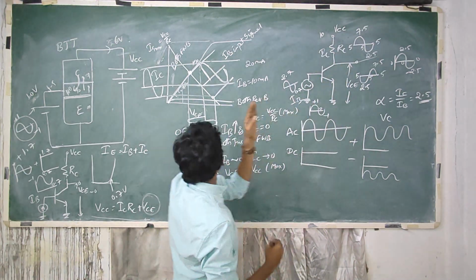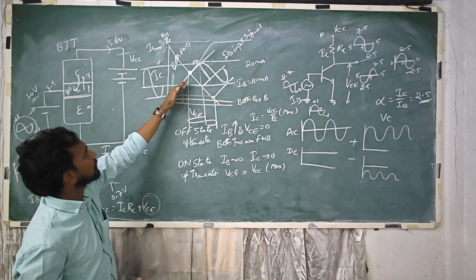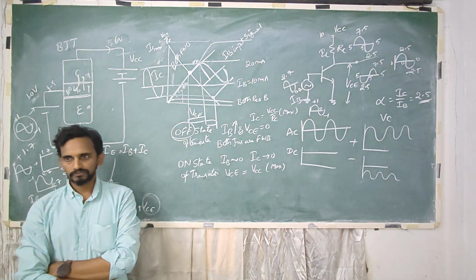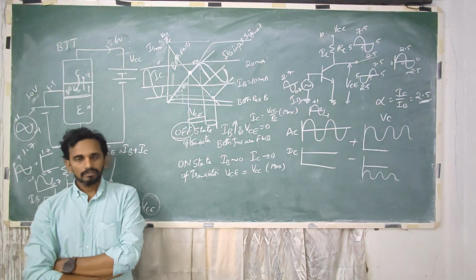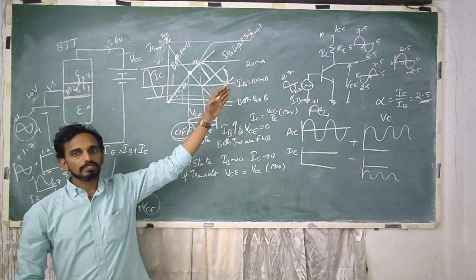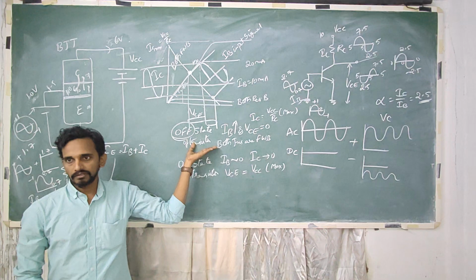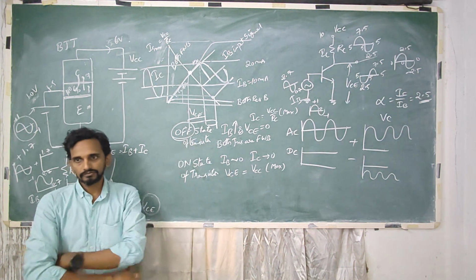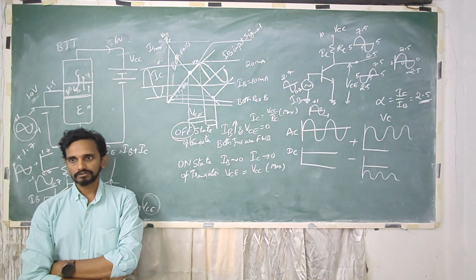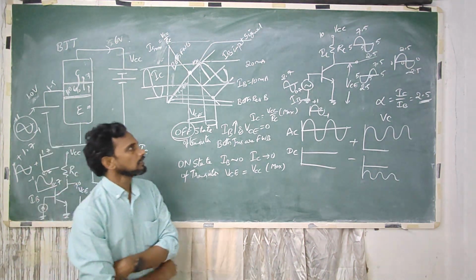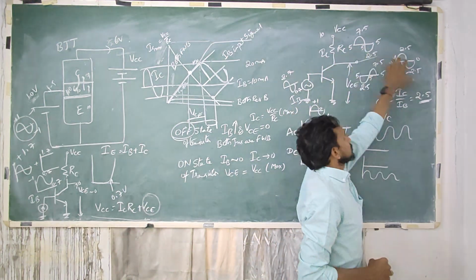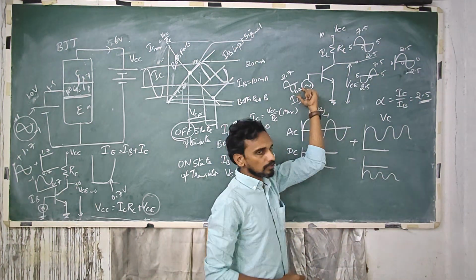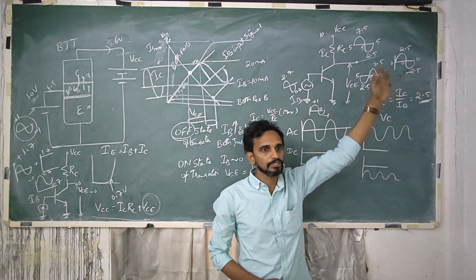So if the input current becomes far and far more higher, what happens? Transistor goes off. If you cross a certain limit, as the input signal becomes higher and higher, the transistor goes off. You cannot amplify it further. So what to do? You remove the entire DC component here and add whatever biasing potential required at that level additionally.